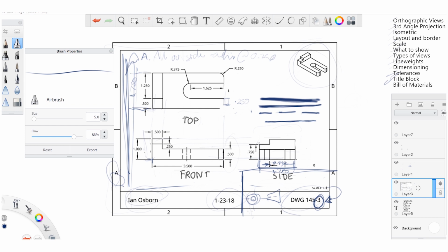You should also have this symbol, the third angle projection, and there are other things as well which are quite important, especially if it's a part drawing, such as the material you want it made out of, the method maybe that you want it made out of. It just depends on your product. You can also include the page size as well, just in case you are sending it digitally and they need to print it off or just need to know for scale purposes.